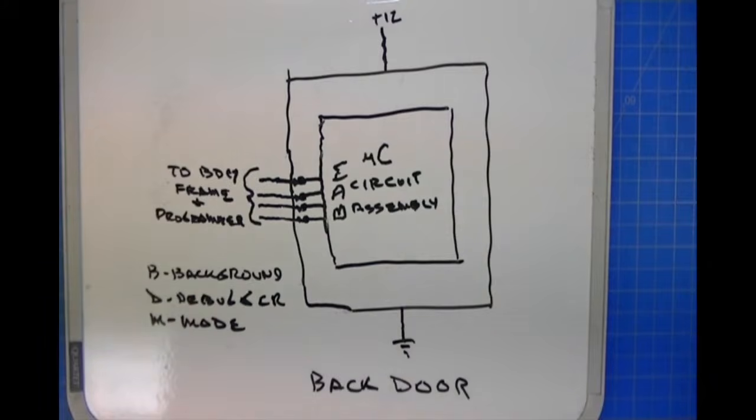The other thing that you can do with the background debugger is, since you are directly controlling in the background, you can directly control the pins of the microcontroller. What that means is, even though, let's say you've got an external EEPROM, the background debugger is capable of reading by manipulating the pins on the processor, because it's doing it in the background.